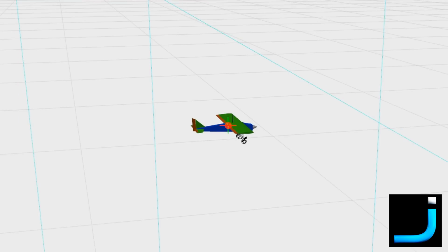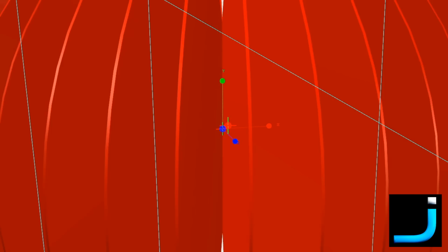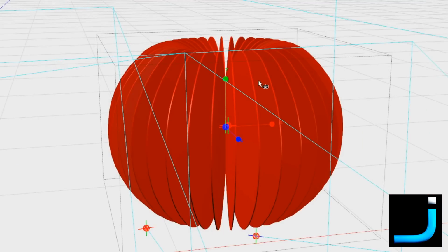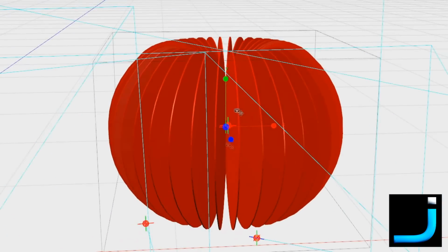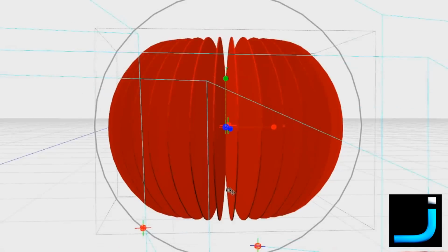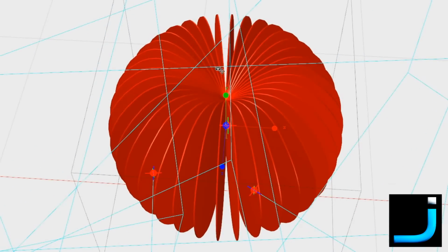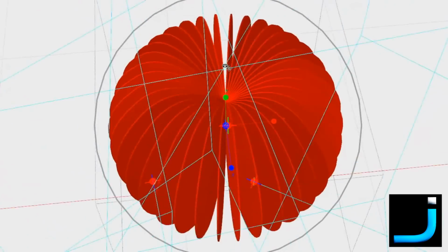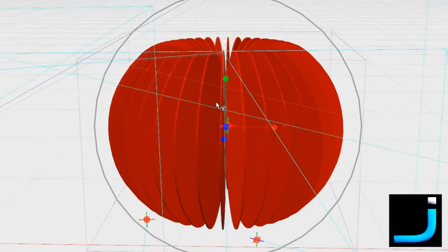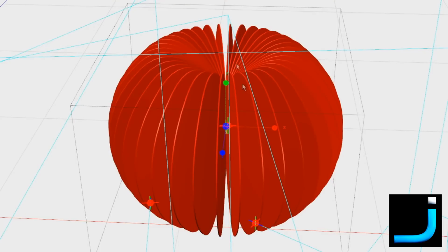So let's have a look at the typical pattern for this particular antenna, which looks like that. Again, this is taken directly from the specifications. A 0 decibel gain antenna would be a perfect sphere, in all directions. Now this is 2 decibels, so there are areas of sensitivity that are lower than others.